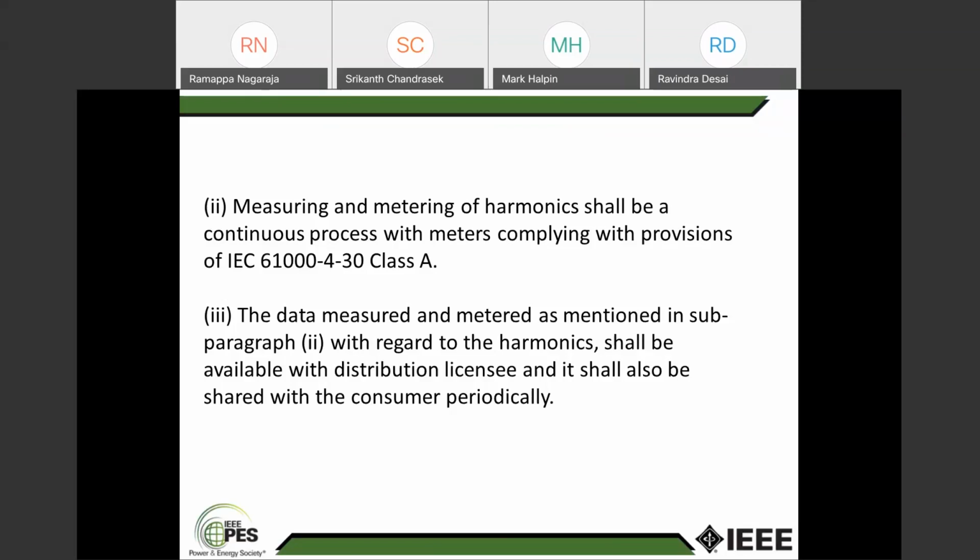In the US, almost all of our significant customers in modern times have power quality instrumentation permanently monitoring in effect in parallel with the energy meters. So it's quite normal to have continuous power quality monitoring for significant customers. In effect, any customer where limit compliance might be assessed is going to have continuous monitoring.